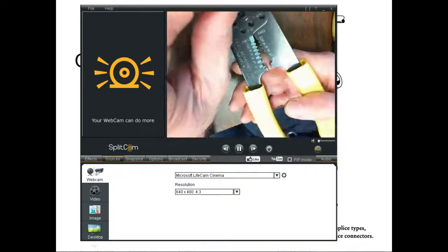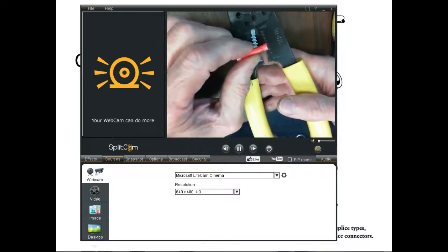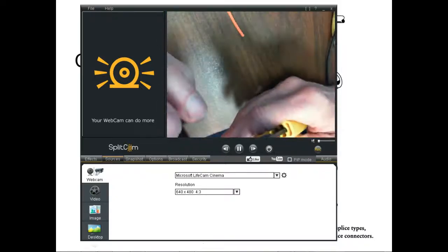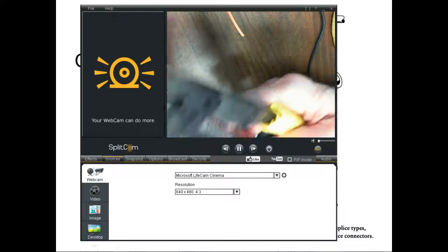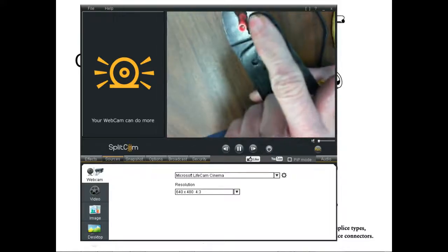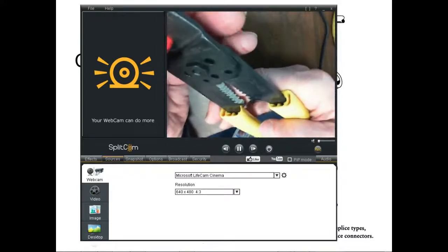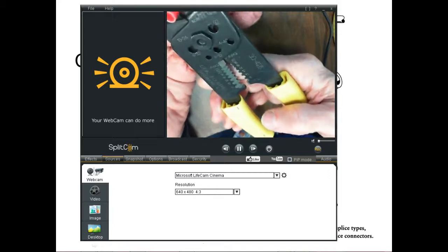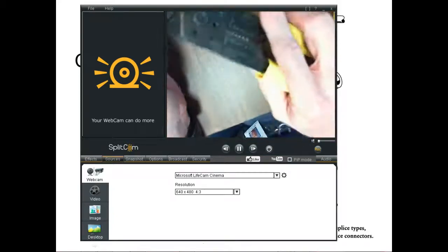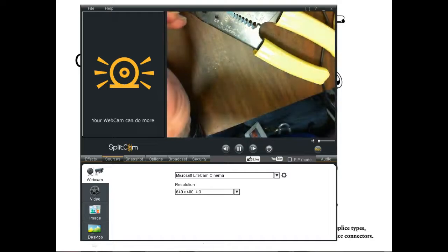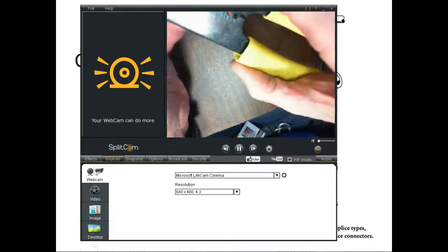I'm talking about the front foot; you want the other one without the thing. One of them is to crimp the conductor, which is bare. The other one is to crimp the insulator back here on the back. So you have two things you're crimping: the wire and the insulator. This is the bare wire.